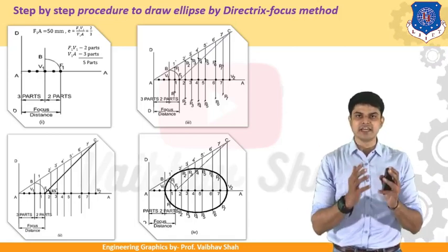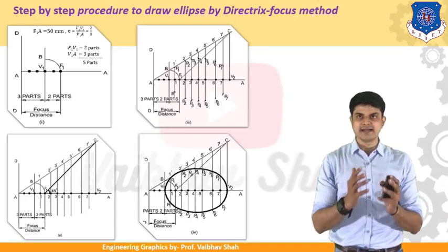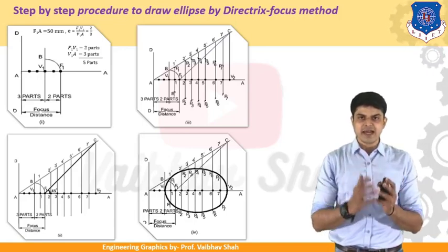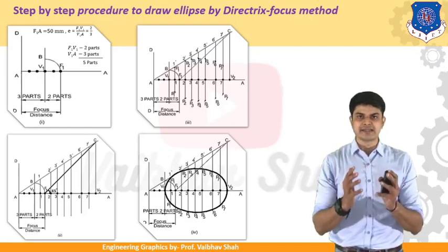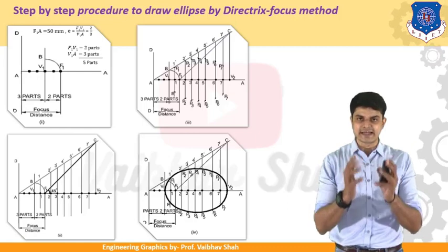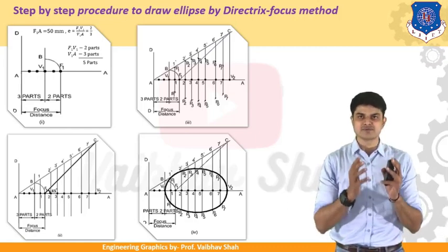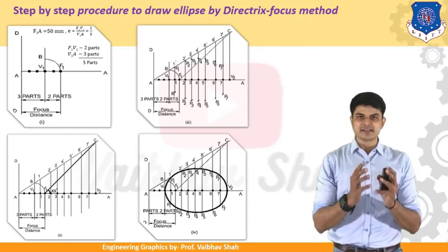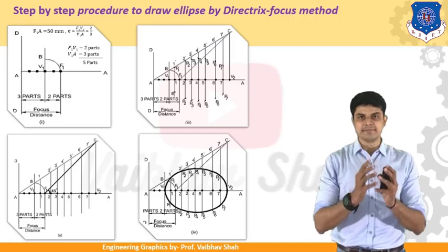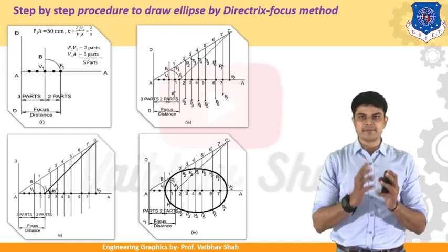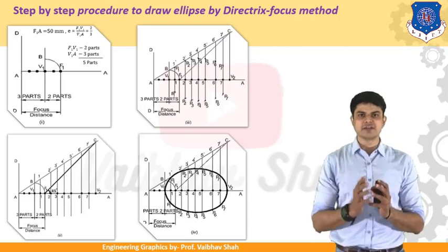Then what do we need to do? Let us take out the rounder, take the radius equal to F1V1, and draw one vertical line from V1 perpendicular to the horizontal line. Thereafter, with V1 as the center and F1V1 as the radius, draw one arc to cut this vertical line. After cutting this vertical line, you should give that point as point B. So let us define that point B. So we have completed the construction for the first figure on my left.